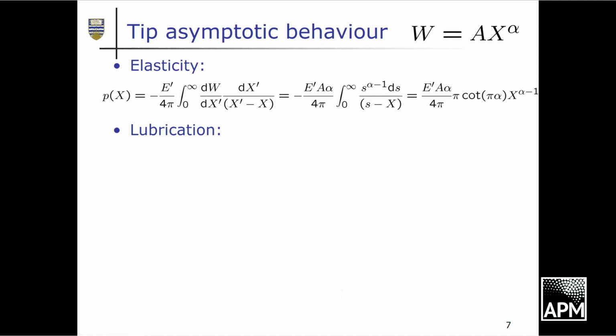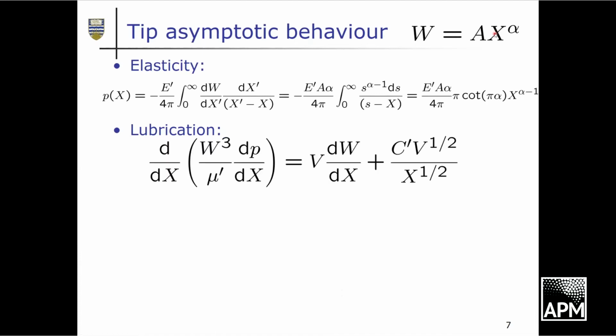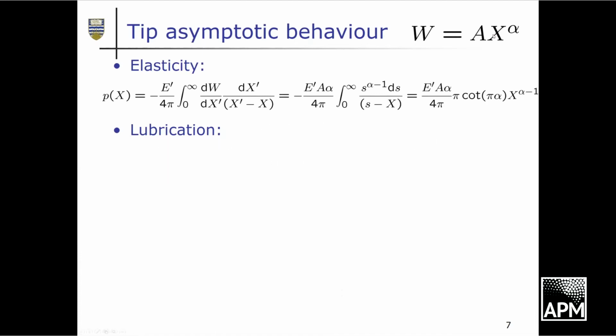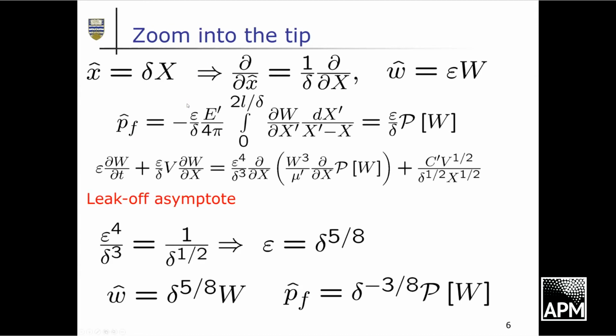Another way to look at this is that it is very analogous to what you learn in simple ordinary differential equations in terms of Frobenius series. You look for a power law solution, x to the alpha, where alpha is a parameter. And it just so happens for the semi-infinite fracture, notice when we let delta go to 0, with L being finite, this thing goes from 0 to infinity.